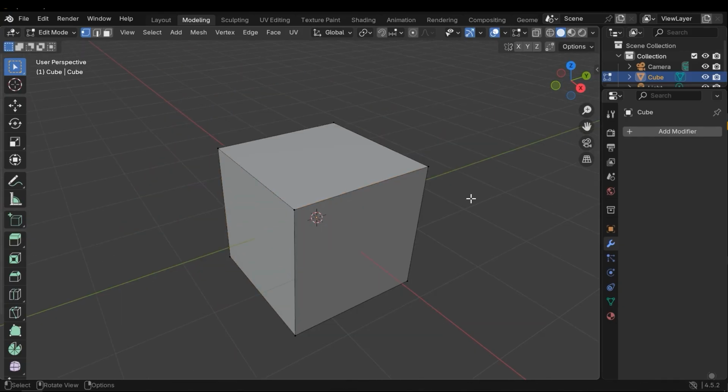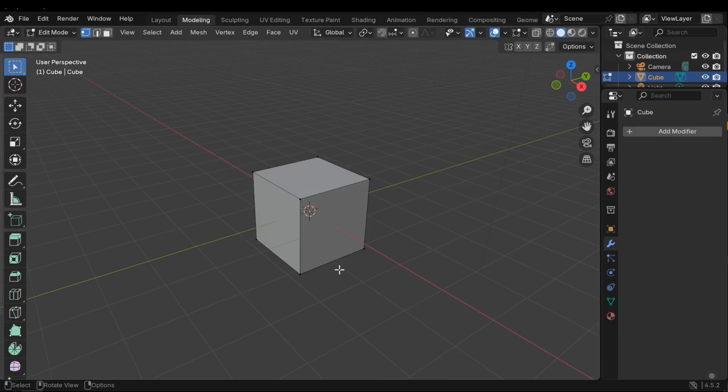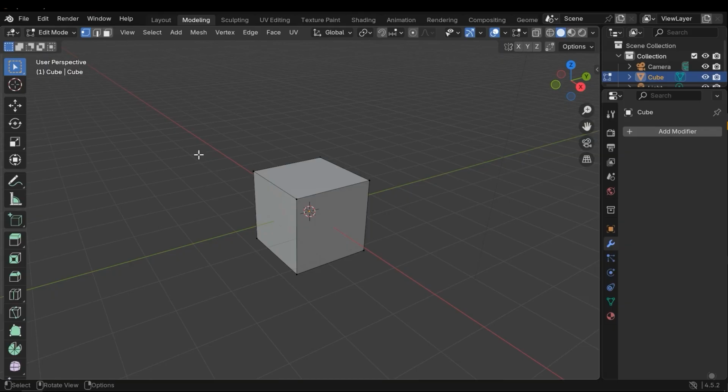Alright, these are the main components of each 3D model. For a complicated model, we have more vertices, more edges, and more faces. For example, if you want to create a pipe, you need a cylinder 3D model and you need to shape it and curve it, and curving it needs more edges. Make sure to keep your polygon and face count small, because a big amount of polygons can be heavy to compute. Alright, now let's introduce the modeling tools.